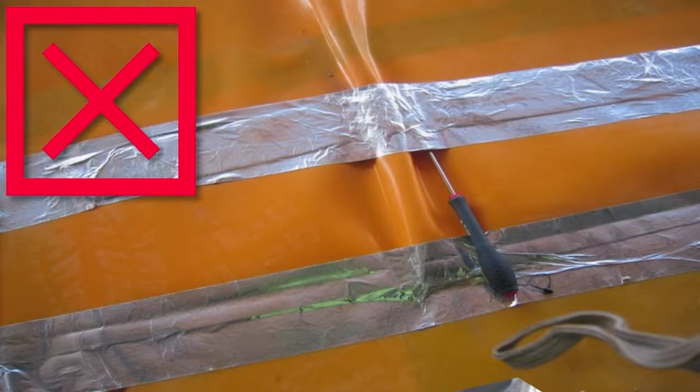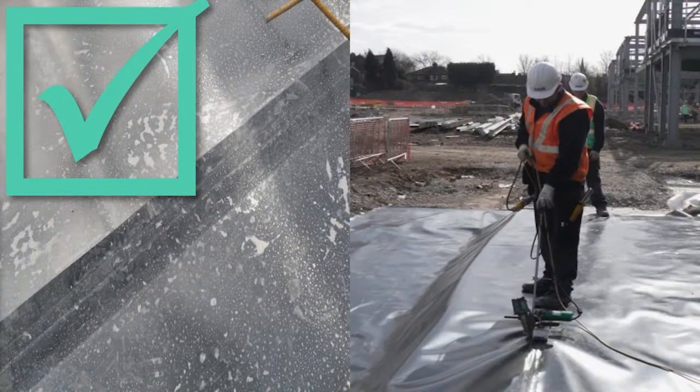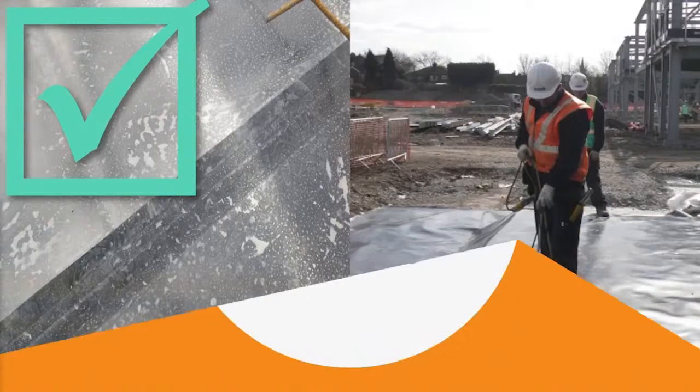The most effective method, and that used by the majority of NVQ2 qualified installers, is to weld membrane joints. This not only saves on the cost of tape, but it's far more tolerant of weather and site conditions as tape adhesion is not an issue. Successful tape jointing requires a clean and dry membrane surface to joint, and temperatures within the tape's operating range, typically 5 to 30 degrees.